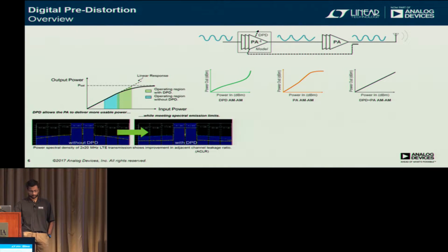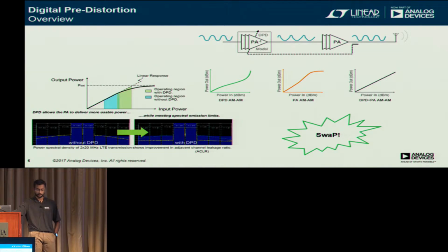So you have a nonlinear PA that you've now linearized, basically giving you margin to spec, so your spurious emissions aren't that bad. You have a metric called ACLR, adjacent channel leakage ratio, that you want to push down. There's a 3GPP spec for that. And you get better system efficiency. Sounds great. And this also means that your SWaP has now gone down. So it's a win-win-win, right?